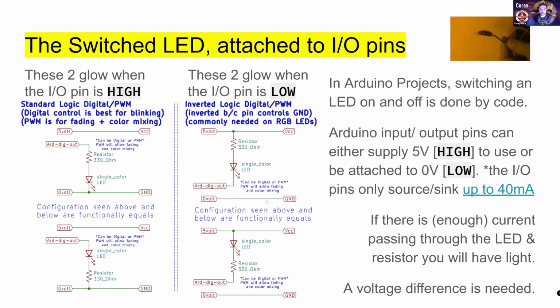I just put the line there to show that it isn't involved. Right. So if you were creating a system where a ground was needed, an Arduino always has the ground pin. This is just saying that you wouldn't need to attach to it. Interesting. Okay. Yeah, because you're using the digital output pin as the ground when you switch it to low. And when you switch it to high, it's serving as another 5 volt pin.